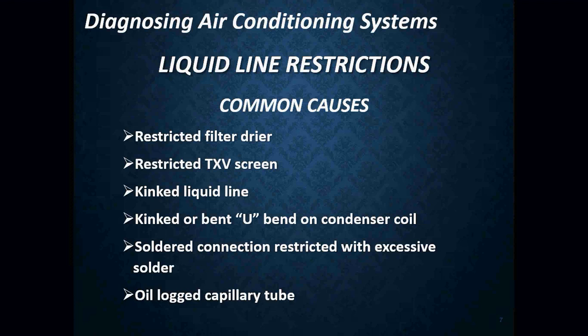and debris, especially if somebody dragged the refrigerant line through a pile of dirt while they were installing it, or you got a burnout or something going on inside the system that will cause these things to clog up. A kinked liquid line, which is very, very common. I hate to say it.